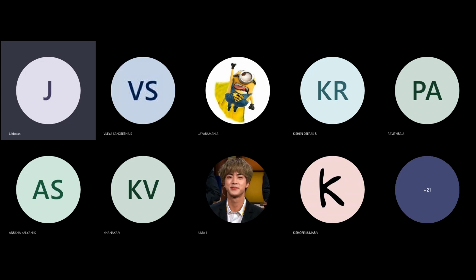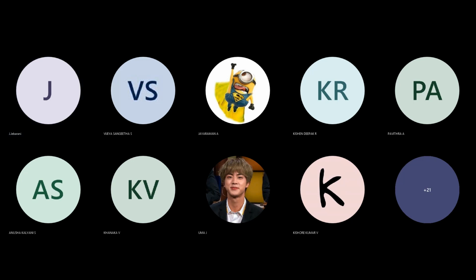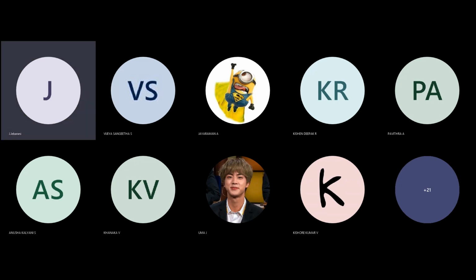The various multicolor patterns can be produced not only by controlling according to the time chart, but also by controlling the temperature of the heating cylinder, the pressure, the speed of injection, and so on. Various patterns can also be obtained by using different structures of detachable attaching chamber, which is obtained by the injection control.